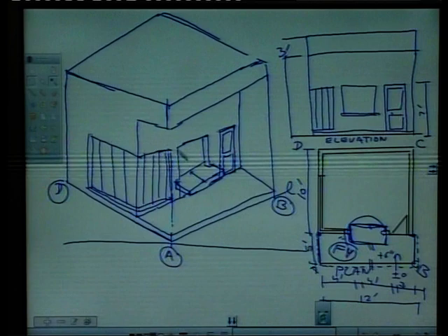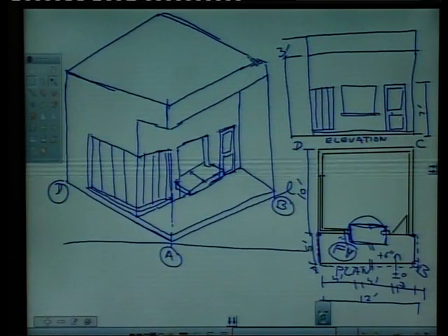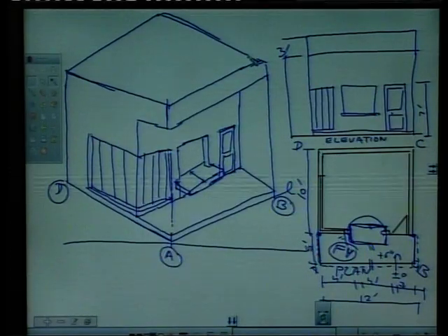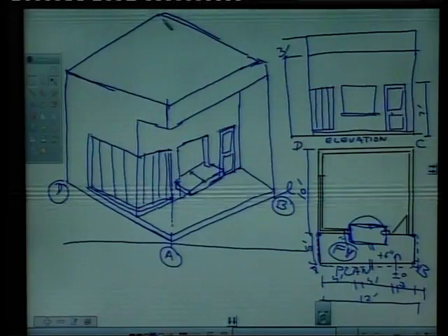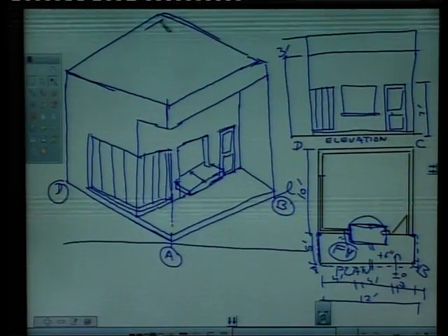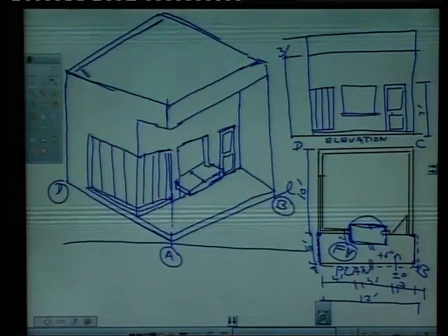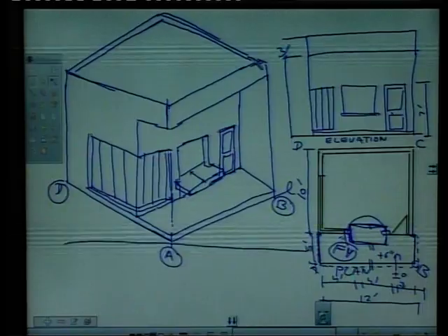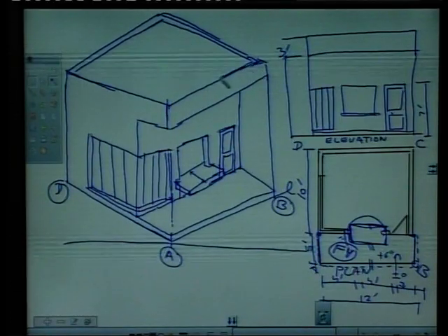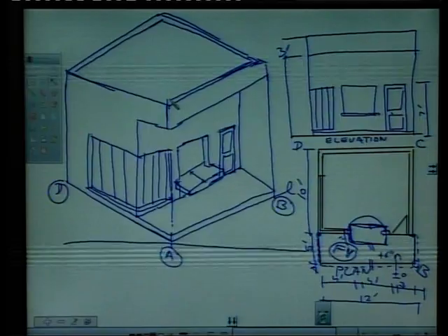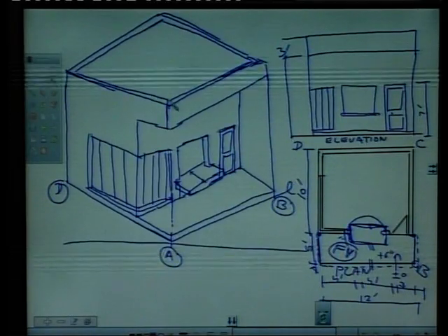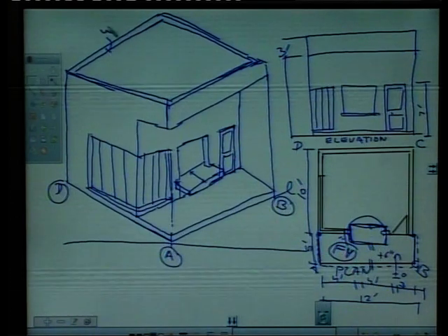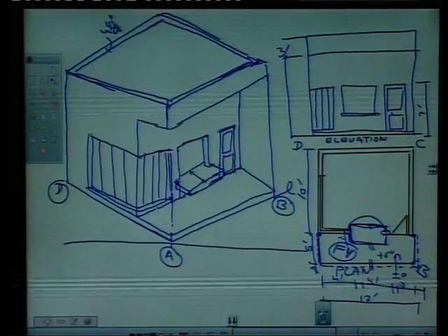Now, how to draw parapet walls of the roof? Say at parapet we have a 4.5 inch or 9 inch wall. Just draw wall here like this, parallel line like this, another parallel line like this, right, one parallel line like this and one parallel line like this, right. Take this dimension as say 4.5 inches to the scale, right.